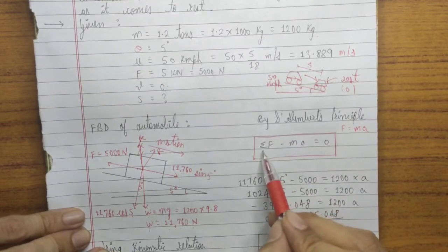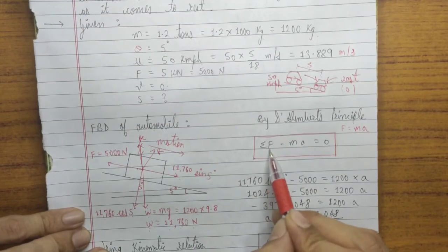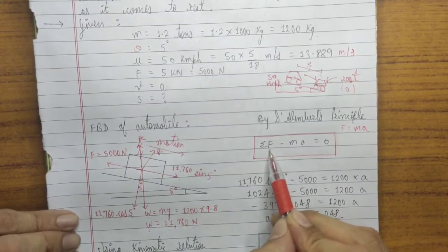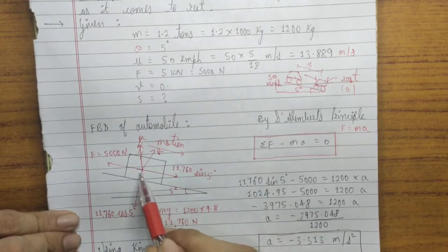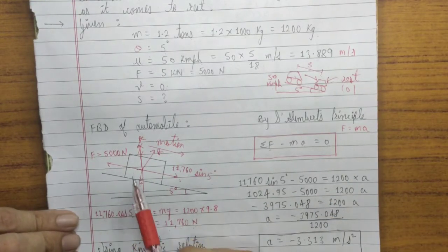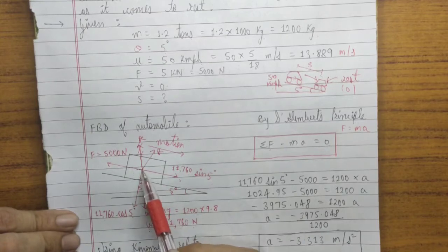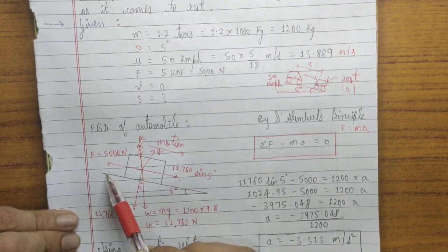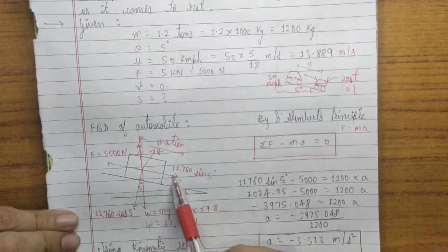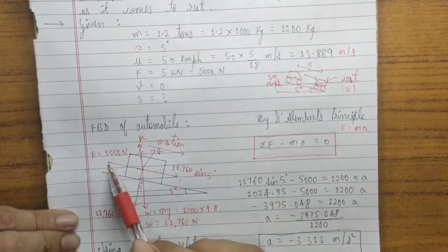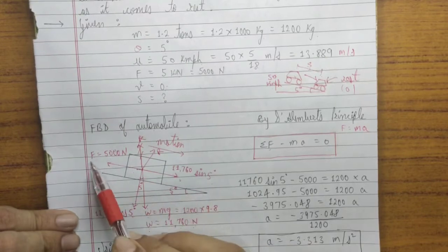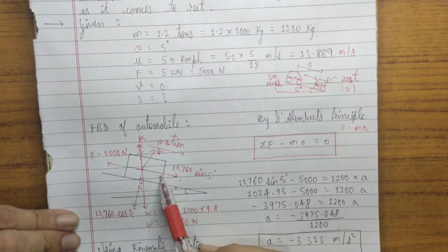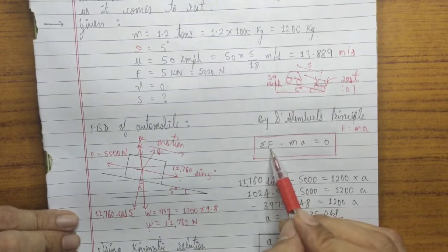Okay, now understand what is summation F. Now summation F means summation of all the forces. Okay, but which forces? The forces which are causing the motion of this particular object. Since this object is moving in downward direction along the incline, okay, it will move because of the forces along the incline. Okay, so these are the two forces, the weight component and the frictional force. These are the two components which are causing the motion of this particular block. Okay, so what will be summation F?